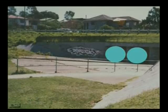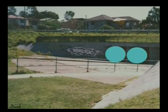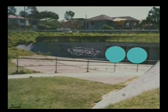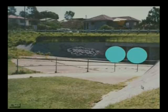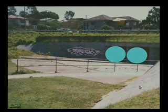This figure I have picked up to show how a slope is. These are nothing but the vents. Through these vents we can also provide pipes. This slope you can see here, is it not? This is the slope filled with some granular material, and this is overlain or packed with a thick layer of stones. That is what we call revetment. Such slopes are there on all 4 sides, 2 here and 2 similarly on the other side. So there are in all 4 slopes.